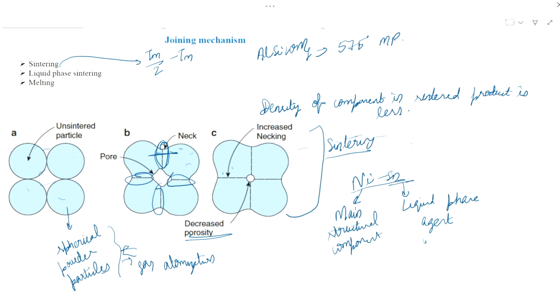The melting point of tin is much lower than nickel. So when the temperature is increased to, suppose, 200 degrees Celsius, the tin will be in molten form. So this will increase the wettability of the powder particles. Ultimately, the sintering quality of the product will be higher as compared to normal sintering. That is why we use liquid phase sintering.